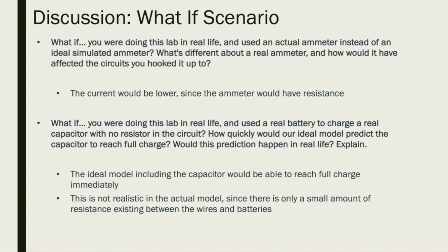Next, what if we were doing this lab in real life and used a real battery to charge a real capacitor with no resistor in the circuit? How quickly would our ideal model predict the capacitor to reach full charge? The ideal model would be able to reach full charge immediately, which is not realistic in the actual model since there's a small amount of resistance existing in the wires and the batteries.